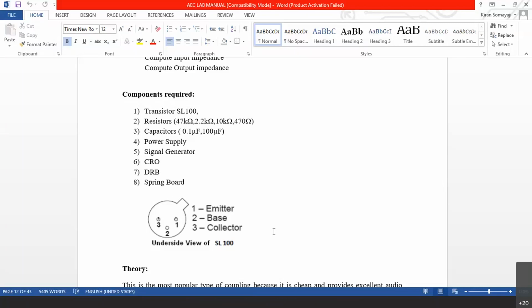So normally when they manufacture transistors, the collector region is always the largest of all the three. Now when the transistor gets heated up, as the collector is larger, they connect the collector to the body itself, so that if it is a metal package, heat can be easily dissipated into the atmosphere.